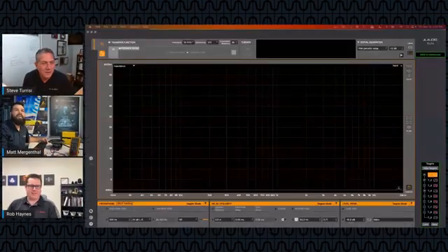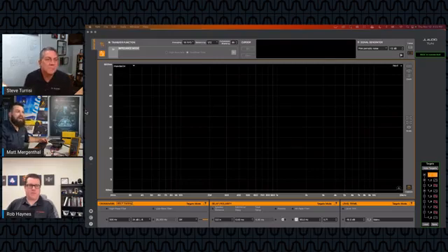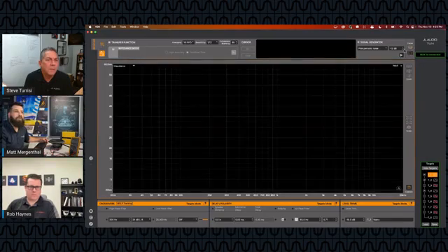All right, so here we have the Tune software open. We're in the impedance graph right now. How'd you get there, Matt? In the top left corner of the graph, I simply selected impedance from our graph type combo box. And I've made it full screen. You can do that using the panes button in the top right corner of the screen. What we need to do in order to make these probes work is turn on what we call impedance mode.